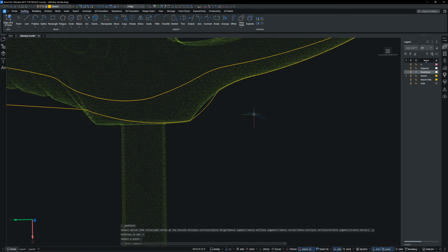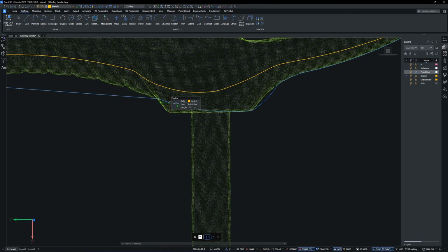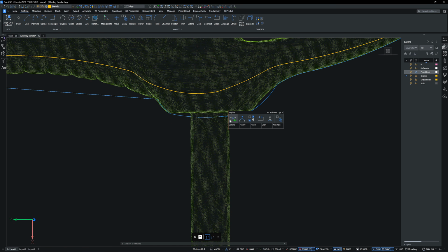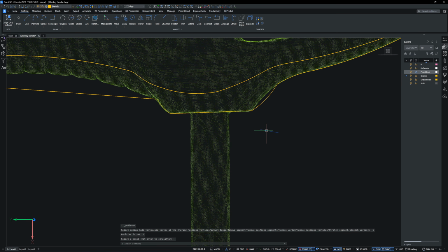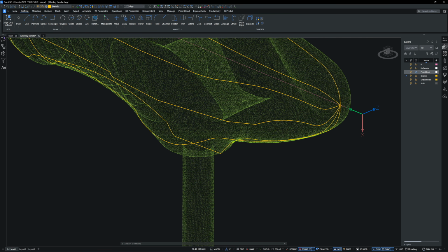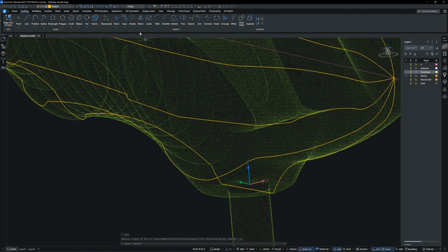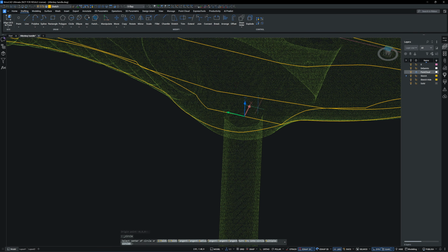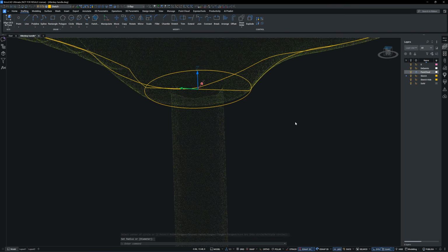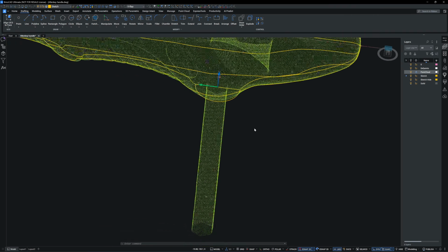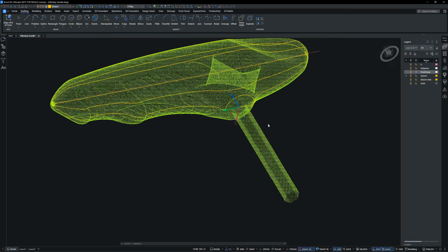I ran the remove bulge command to turn the curve into a straight line, then add a vertex and adjust the existing sketch to fit the finger rest area. I will switch back to the world UCS and move it to the center of this line to create a circle, then trim it in half. This section can't be replicated with solid modeling. It has to be built using surface modeling.